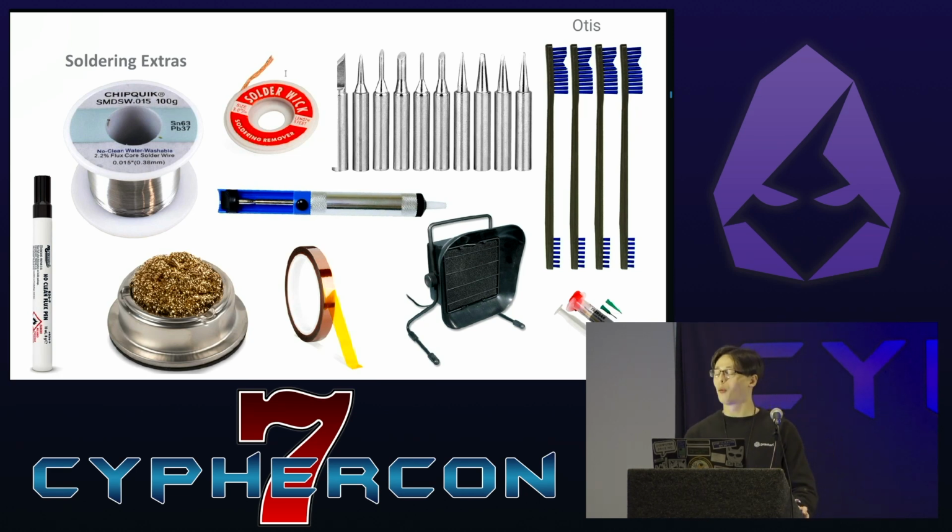Now with soldering, you're always going to put solder where you don't want it. So that's where the solder wick, and then below it the silver and blue tool called the solder sucker, come in. With the solder wick, it's just a twisted copper braid, so you can place it over the solder you're trying to remove, hold the tip of your iron on it, and as the solder melts, it'll get soaked up into the wick, and you can remove it.